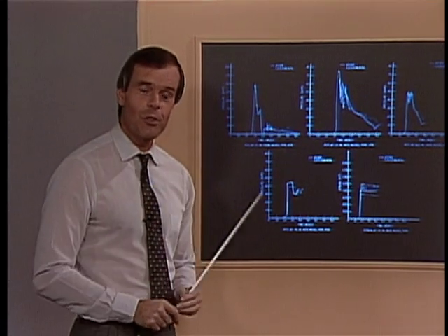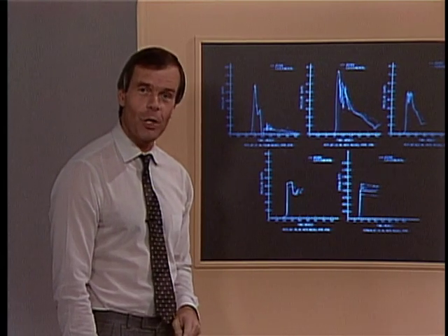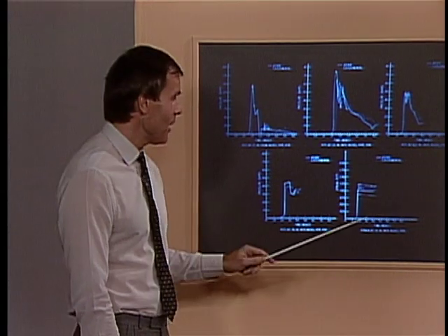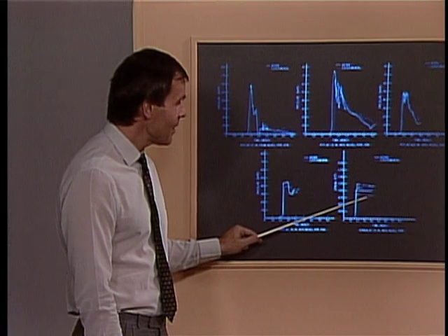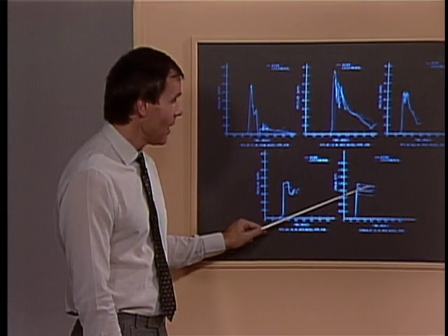In the ADINA solution, of course, we used an axisymmetric model, and that axisymmetric model only gives us one hoop stress. One hoop strain, I should have said. And that hoop strain, as you can see here, lies quite nicely within the experimental results obtained by the Stanford Research Institute.